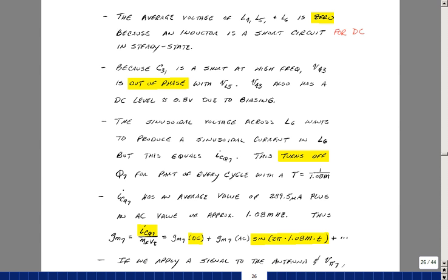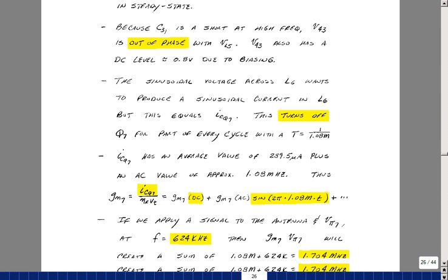So what you have now is a current that's flowing into the collector of transistor 7 that has an average value and then an AC component of 1.08 megahertz. So effectively GM is changing, has a constant part to it and then a part that's changing. Now GM is going to multiply V pi of transistor 7, and that's going to be my received signal.